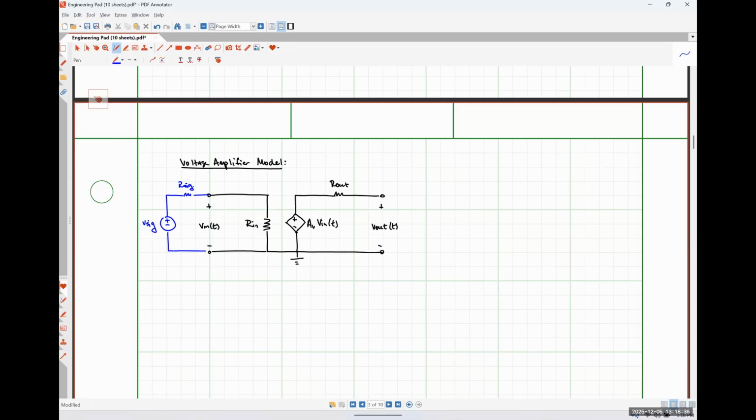What I have on the input side of this amplifier is a voltage divider, right? So V in, the signal that's applied to the amplifier, is just going to be V sig times Rn over R sig plus Rn. So the larger Rn is compared to R sig, the input signal that's being applied to the amplifier terminals looks closer and closer to actually V sig, so that the internal resistance of the signal source doesn't matter, okay?